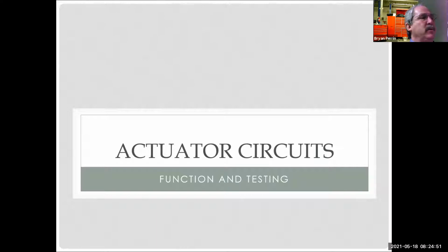Okay, so actuator circuits, function and testing. An actuator is a load. If we envision a series circuit, and most actuators are in a series circuit, there's a few parallel circuit options where we turn multiple actuators on at the same time. That's with some old fuel injection systems, but most actuators are in a series circuit, and they're the load for the circuit. So that means I have to have a power supply, conductors, and the actuator is my load.